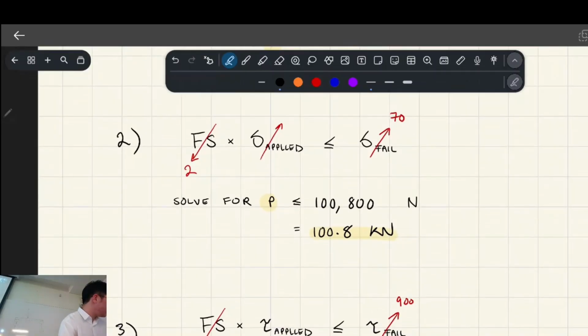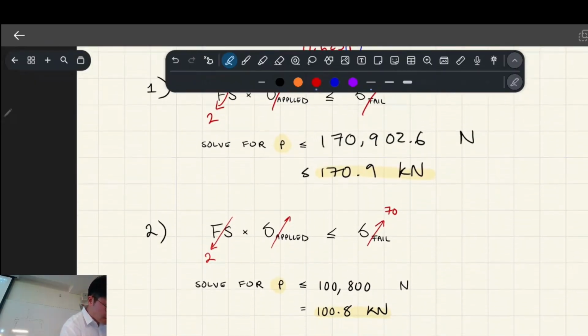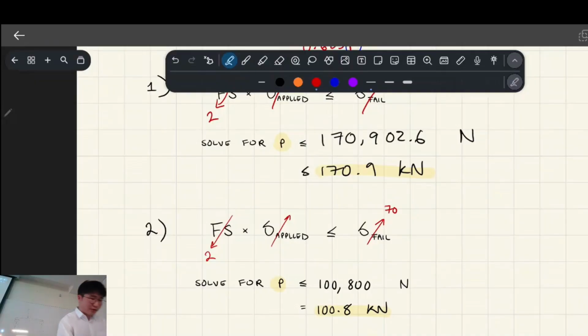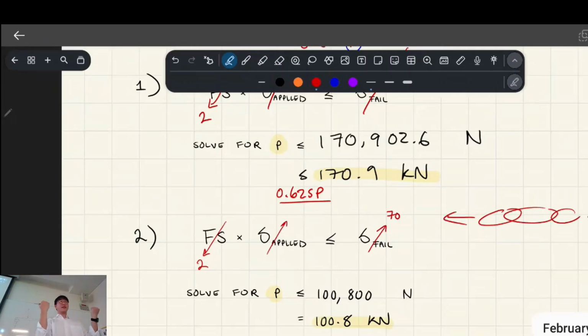And then similar idea, now we're talking about the aluminium block. We have the same force that's going through the whole system. This is traveling from one link to another, so it's the same force. If I had 3 links and I'm pulling on it, it's the same amount of force traveling through all of them, but they might be experiencing different stress levels because the cross-sectional area of these links could be different. Does that make sense?